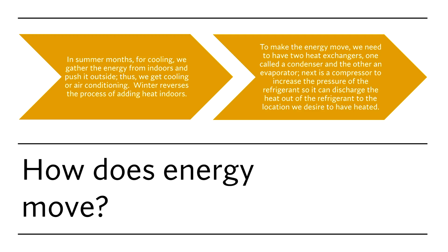Okay, the heat pumps do work pretty well down to minus 20, and even with my own experience, I've pushed it even down to minus 27. There's some efficiency things there, and I have plans for another set of videos with some real data that discusses the efficiency of heat pump systems. Anyways, so generally we move heat from hot to cold, or if you want to think about it, inside to outside, as long as we can create a temperature difference in doing so.